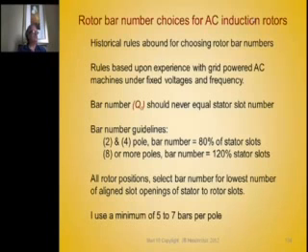But the rotor poles aren't glued there. They're slipping, so the specific bars that have the current going in one direction versus the other direction are changing right at the pole transitions, right at the plus and minus current transitions. So they're changing all the time. The current is actually reversing in one bar between the two poles all the time as it rotates in accordance with the slip.